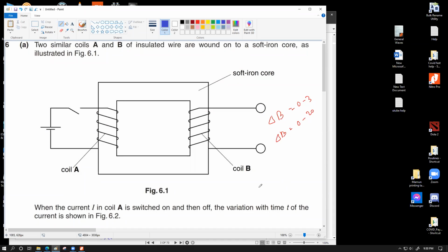So this is about why we need the soft iron core. The idea of lamination is important. If we have a setup like this, we can choose these wires to be bare wire because there is a gap between them. But if we use bare wires without insulation around the wire, we have to make sure that the soft iron core is coated with an insulator so that current doesn't get short circuited through this metal, because this is basically a metal. So you cannot essentially make current directly flow through this pathway to the output coil, because that will be a short circuit. We want electromagnetic induction to work through the soft iron core, not the actual physical current.